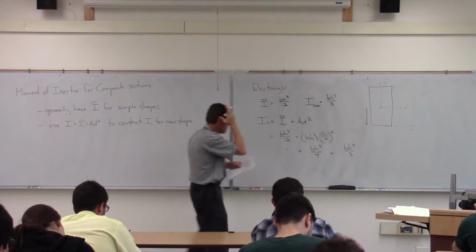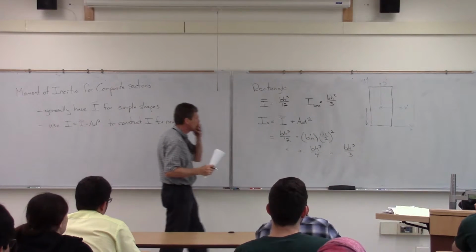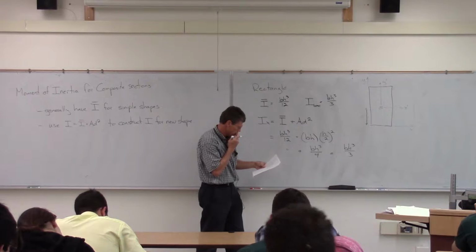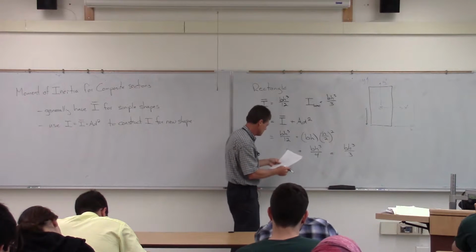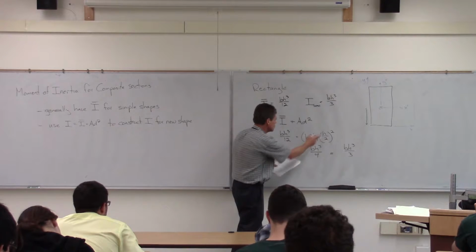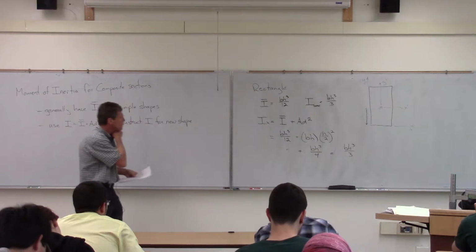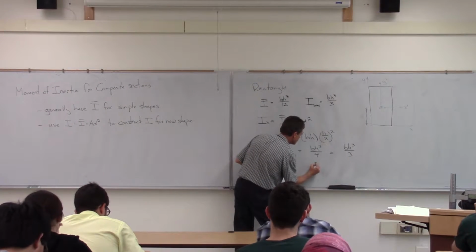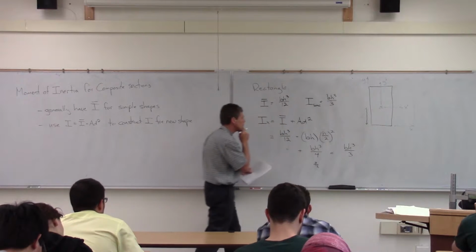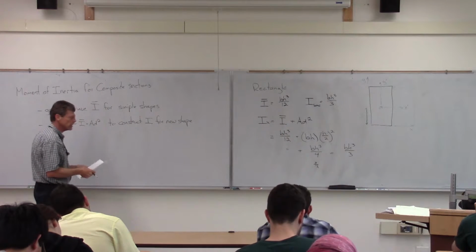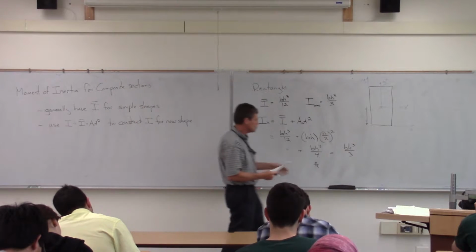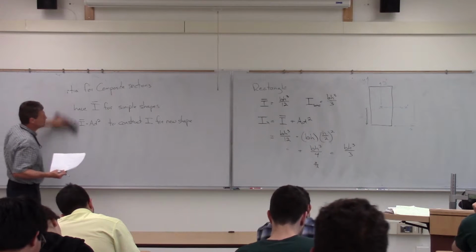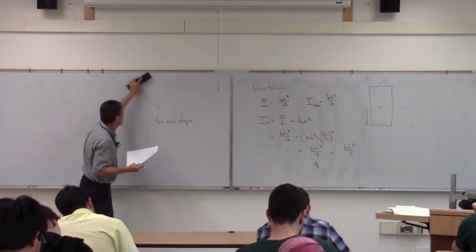And when we just walk through that math, what we'll find is, with the BH, we have h cubed there, we'll have an 8 there. And did I lose it? No, that'll be a 2, sorry. 4. Another way of expressing that would be 3 over 12. So 3 plus 4, 4 over 12 divided by 3, then we end up with the same term. So nothing exciting there, but at least it checked to make sure that that particular base formula that we calculated through integration was correct.